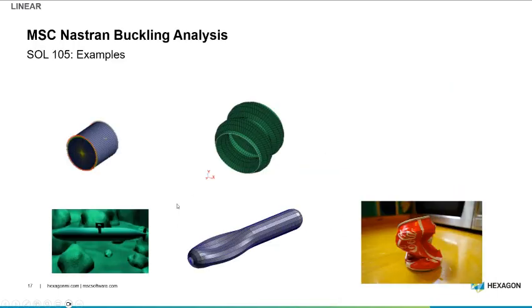Okay, then just some examples further on from buckling. So if you have some kind of a structure that we try to load, there's a very coarse mesh, but you'll see this buckling shape occur. Something like a submarine, its failure mode isn't so much compressive stress as it's buckling. So, and there's all kinds of ribs in there that stiffen it up, but at a certain pressure level, something like this happens.